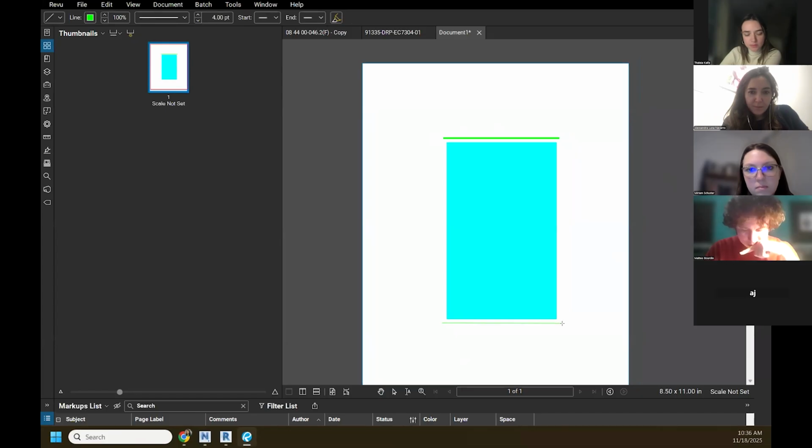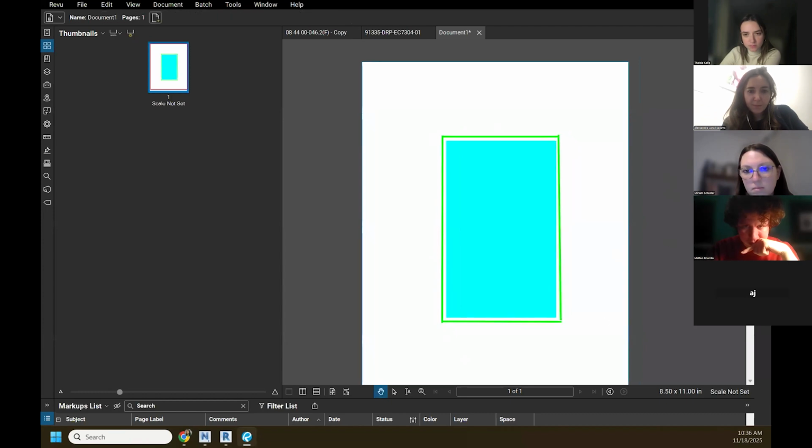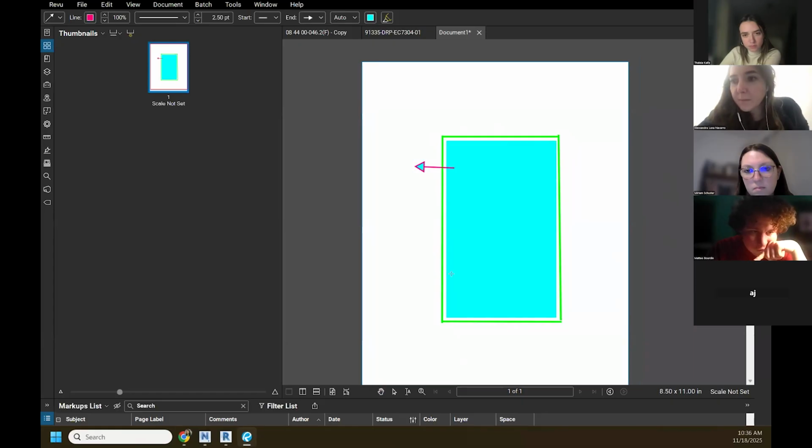We have the transoms and then we have the mullions. It's almost like a punched window on one side. So the mullion is attached into the structure using some fasteners. I will assume at least one of these fasteners is slotted, so it allows for some movement.